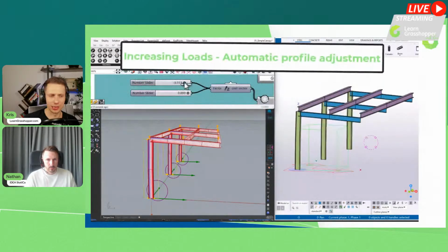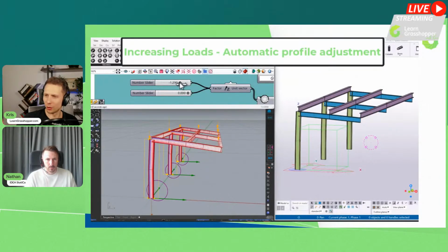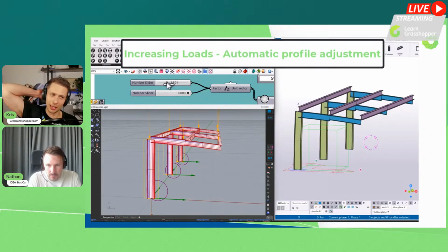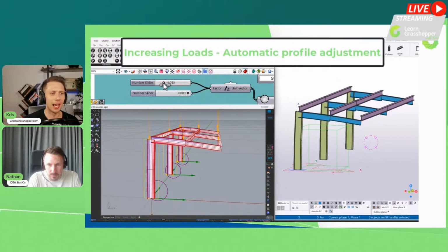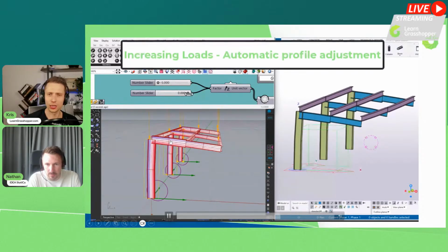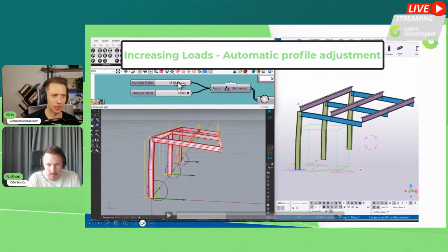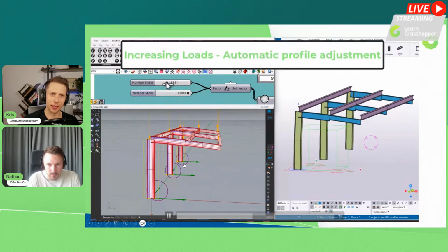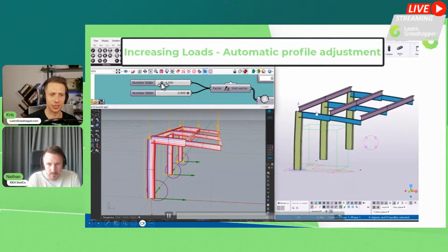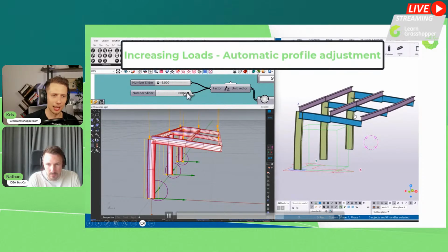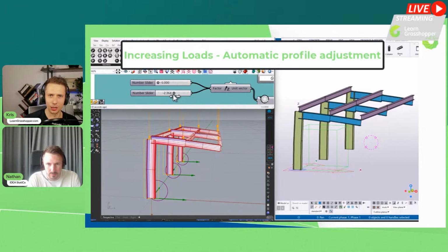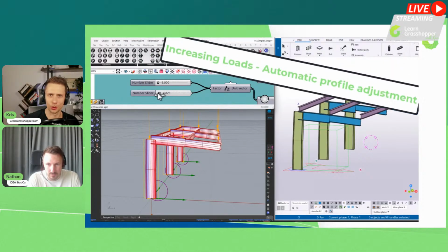For those who are interested, Karamba is a really great tool, especially in preliminary design. If you're just making load changes, adding them with a slider, you can see how fast Karamba is: the cross sections are changing and making checks every single time you make these changes. And we can see this applied also with all the deformation in Tekla. So this is really something cool to see.